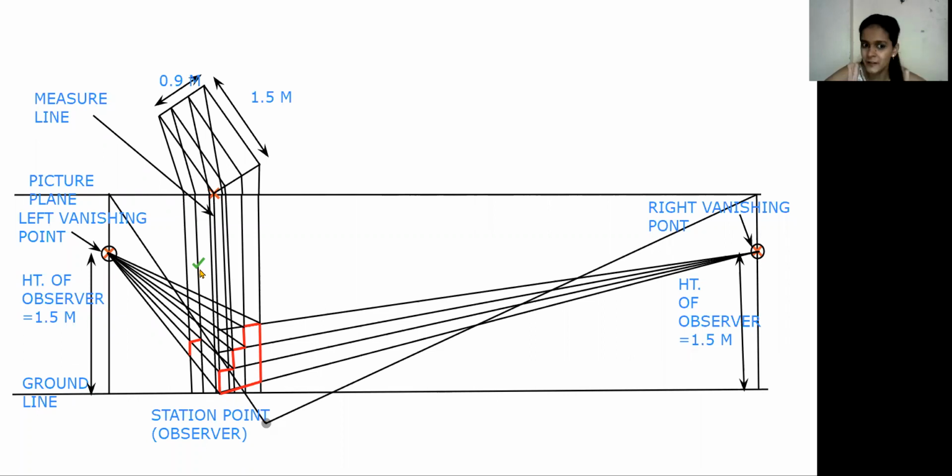After that, the riser will come, and it is between which two inclined lines? This riser is between this line and this line. Okay, so our other riser will also be on this vertical line and between these two inclined lines. So draw our riser. After the riser, there is again a tread.